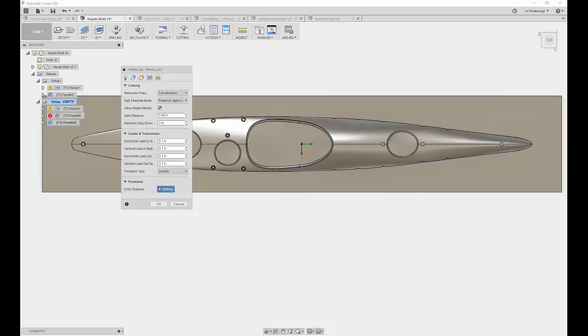I can chime in. I've tested it quite a bit, and I would say just using a Haas as an example, a little DM1 can move around a lot quicker than something like a VF8, right? So the column on a VF8 takes more time to move up and pause and move over and pause and move down and pause. That's what I was saying earlier. I would say 20 to 70% is the window that I usually find, and 30 to 50% is where I usually find myself leaving it.